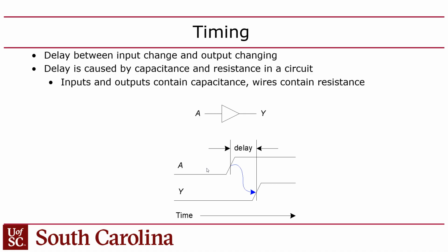fundamentally, the way digital logic works is by charging and discharging capacitors, essentially. And the time it takes to charge a capacitor up, it turns out, is the capacitance times the resistance. It's RC delay. It seems like, wait a minute, resistance is ohms, right? Capacitance is farads. And when you multiply those together, you get seconds? But yeah, that's just how it works out, believe it or not. There's this RC constant.